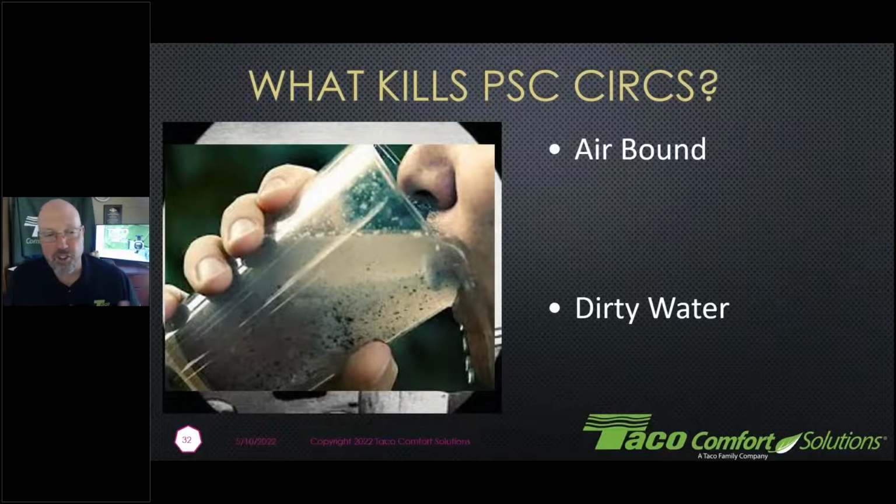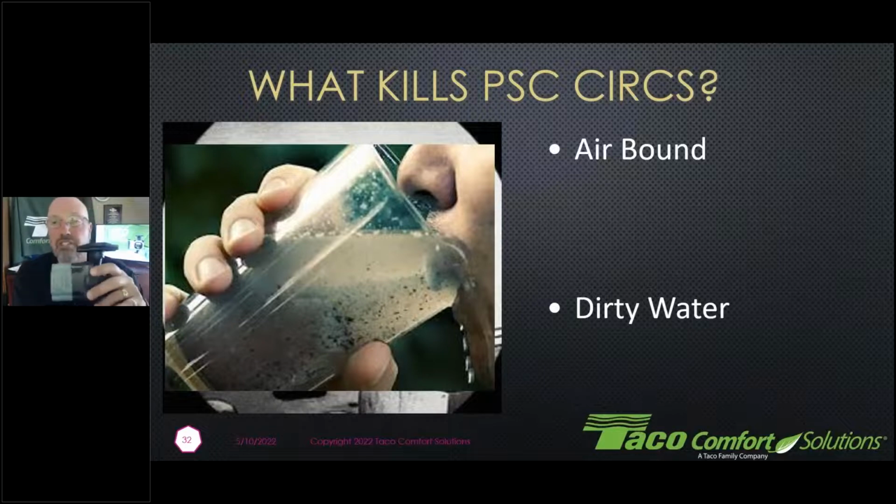Circulators do not like dirty water. Again, it's going to seize things up. And the most common time that we see dirty water or seized circulators, meaning the impeller's not moving any longer, we see that in the fall when we have systems sitting around and the tolerances between your impellers and the cast iron are really, really close, very close tolerances that we have in there.